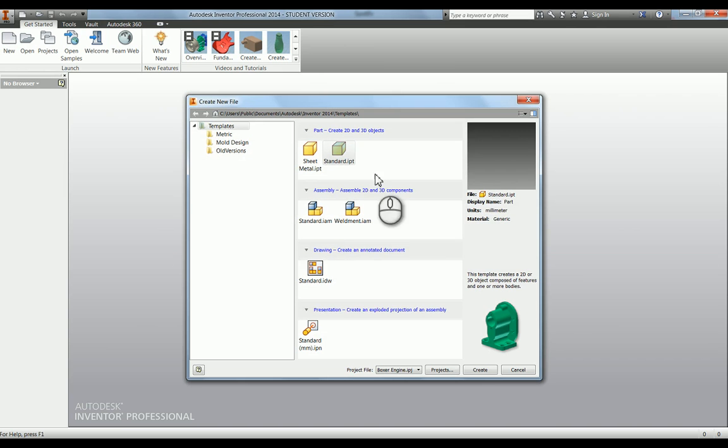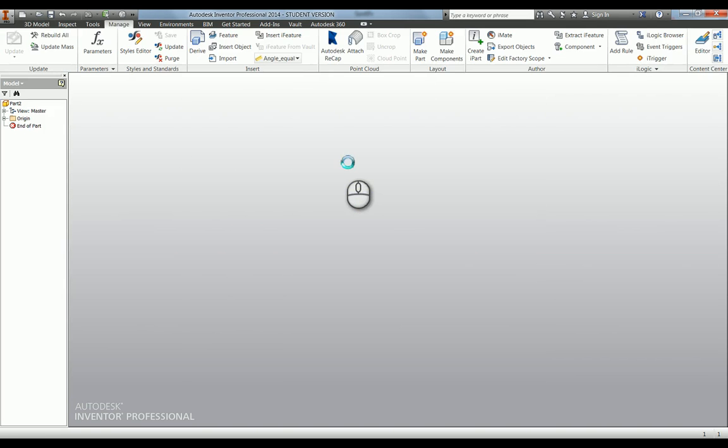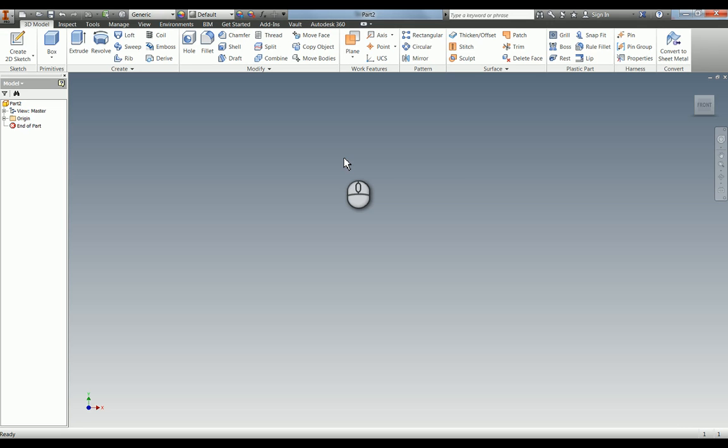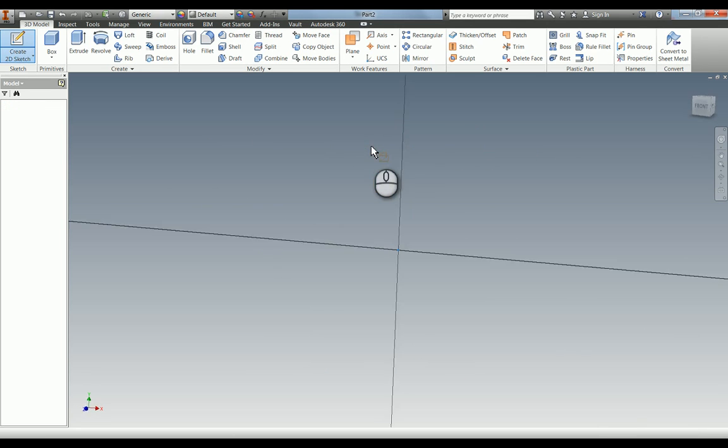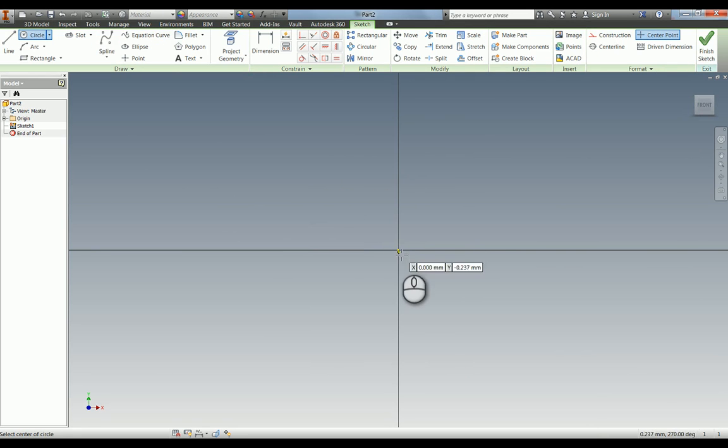So for the selective task for the boxer engine, I'm just going to show you how to add limits and fits whilst you're modelling. So I'm just going to start a new part here, and I'm doing the crankshaft. So I've got the drawing open. So I'm going to put in the shaft diameter here, which is 6mm, but you can see that it's actually